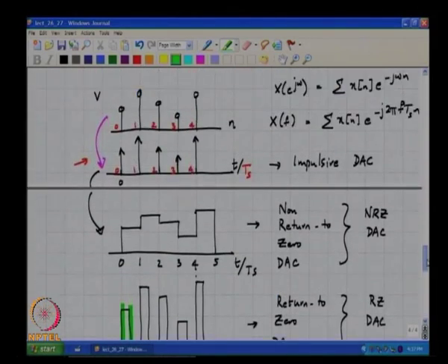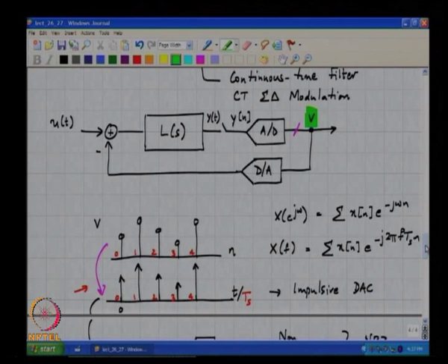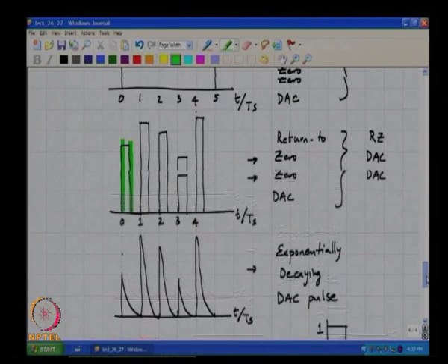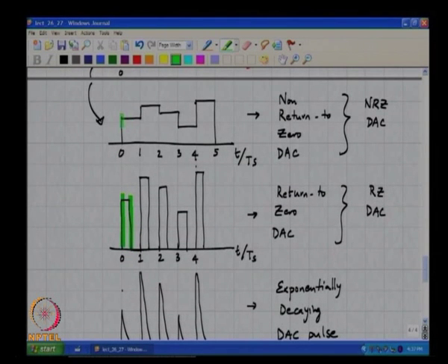Okay. So, as far as we are concerned, when we talk about a DAC, we need to know the sampling rate and the pulse shape, and as we discussed some time back, an ideal DAC will be such that if the code here was 1 and the code here was say 2, the ratio of the 2 steps will be exactly 2, correct.